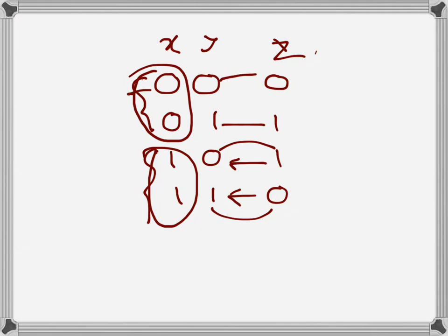So we can use this information to design our circuit. In order to subtract, let's say we want to find A minus B. So we want to do A plus the 2's complement of B. Now, in order to find the 2's complement of B, we can find the 1's complement, then add 1.